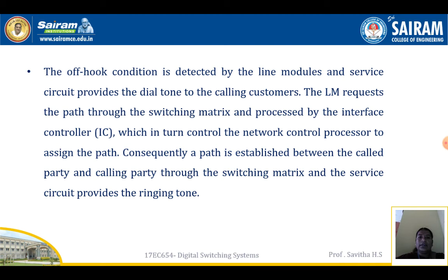The off-hook condition is detected by the line module and the service circuit provides the dial tone to the calling customer. The LM requests the path through the switching matrix, which is processed by the interface controller, which in turn controls the network control processor to assign the path. Consequently, a path is established between the called party and the calling party through the switching matrix, and the service circuit provides the ringing tone.